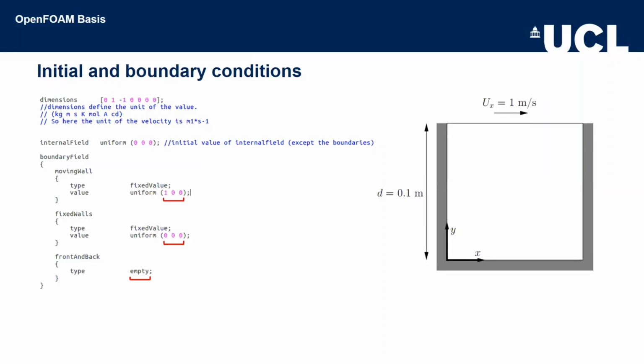So until now, our simulation model has been set up, and it can be understood as the fluid being initialized as static with no velocity in the cavity. And then the upper wall will start moving towards the right-hand side with a velocity of 1 meter per second, while the other walls will stay fixed. The upper moving wall will change the state of the fluid inside as the fluid has viscosity. So if we run the simulation, OpenFOAM will tell us what would happen in such a cavity.